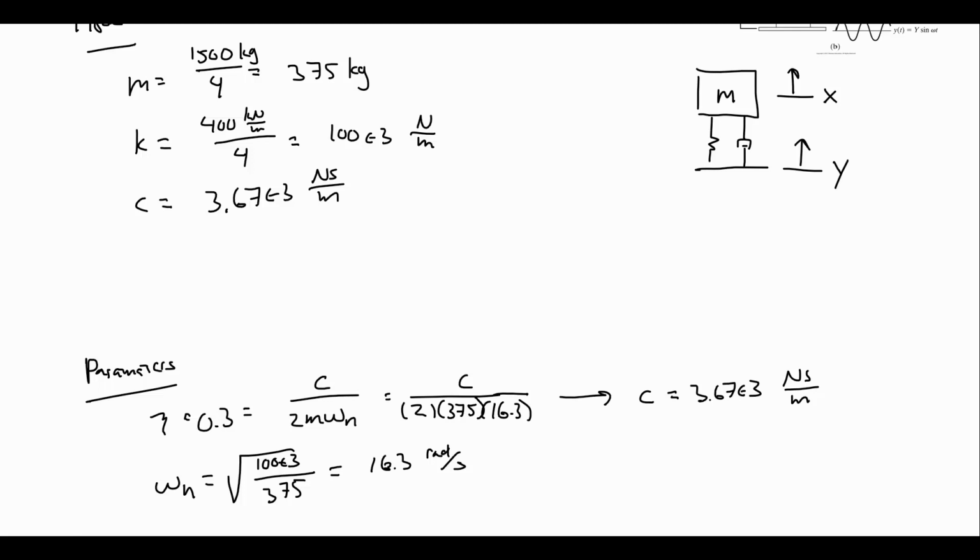So we can identify what we have, which really we're already told what type of system we have. I'm probably not going to write out the actual equation of motion for this because it is a prescribed displacement, but we are told to treat it as a quarter car, so that makes it 1 degree of freedom. It is going to be linear, and it's forced, but the type of forcing is a prescribed displacement, which makes our solution a little bit different. And by the nature of the zeta, it is underdamped.